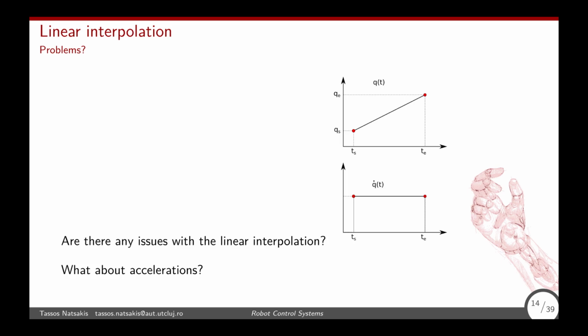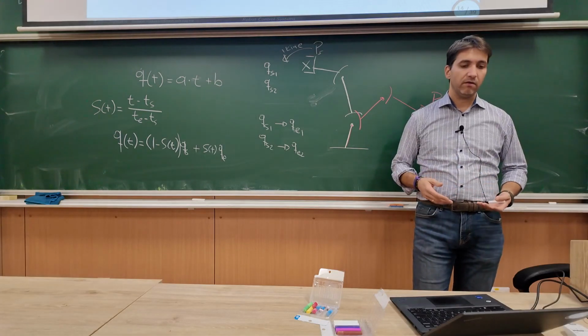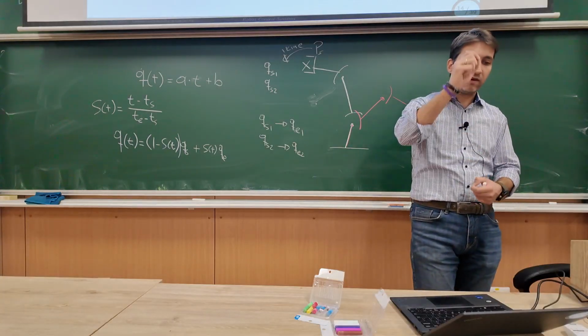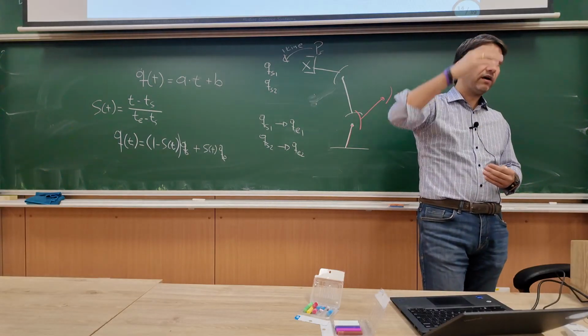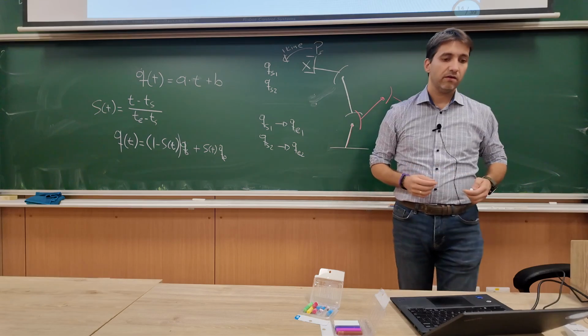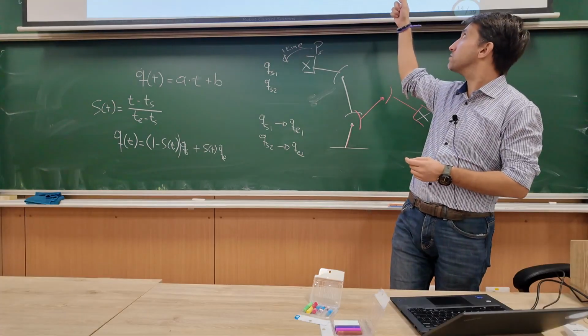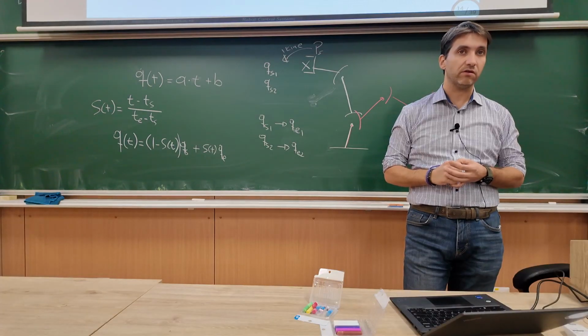With the second derivative, it goes from 0 to a value. I basically have to differentiate this one, right? And here I have a discontinuity, which means my derivative, first of all, is not defined. But in a real case, let's say we don't have a real discontinuity, but we have a very high increase in velocity in a very short amount of time, I will have an even higher increase in acceleration over a short period of time, and then the inverse at the end. I will have a very big drop in the acceleration.